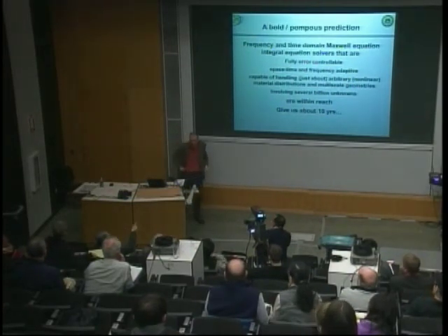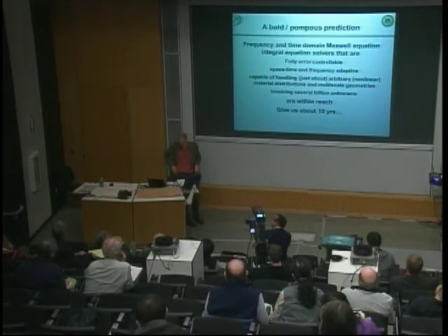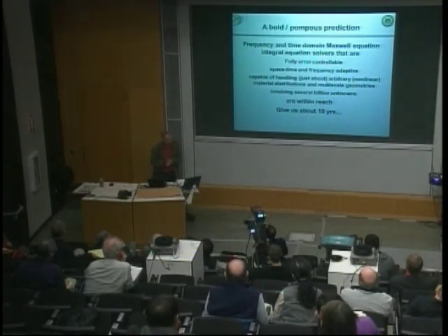You mentioned non-linear problems, but how about dispersive material? Yes. I did not talk about this here, but we've published a number of papers where we apply these time domain integral equation solvers to fully dispersive and lossy materials. Of course, there's a caveat here. We always assume that the response function has a simple description, a few poles and things like that. If that is not the case, well, then you have to bite the bullet and do the full convolution.